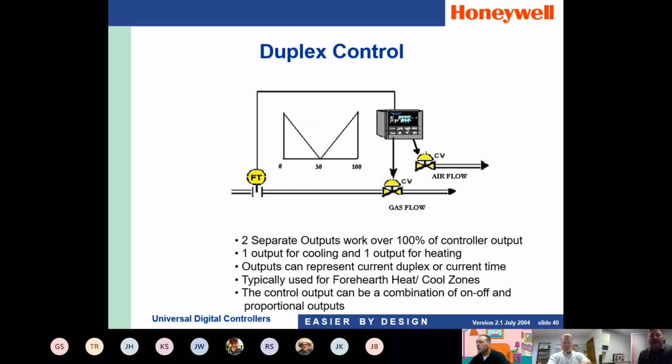In some cases, the process control loop has just automatic type of cooling where you don't have to inject a cooling methodology in the control loop, and the process just controls under its own cooling scheme. But in some cases, you will need this type of action on more intricate control systems, and again, using two independent outputs out of the controller to control both heating and cooling of the process.